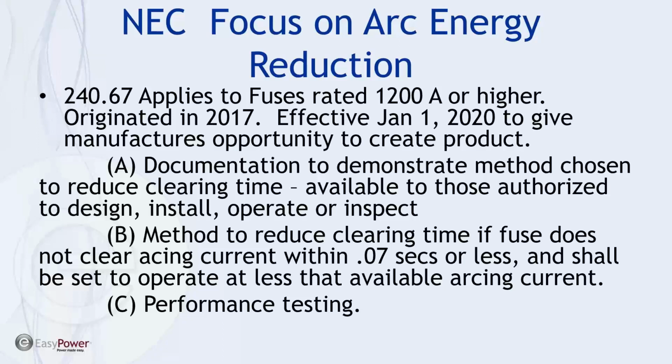And there's a lot in this particular clause. First of all, the documentation to demonstrate the method chosen to reduce clearing time and make it available to those authorized to design, install, operate, or inspect the equipment has to be provided. Second, the method to reduce the clearing time if the fuses do not clear an arc within 0.07 seconds or less shall be set to operate at less than available current, utilizing a list of specific